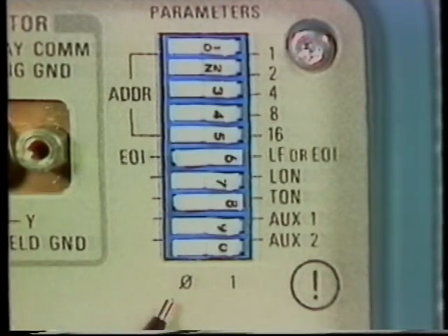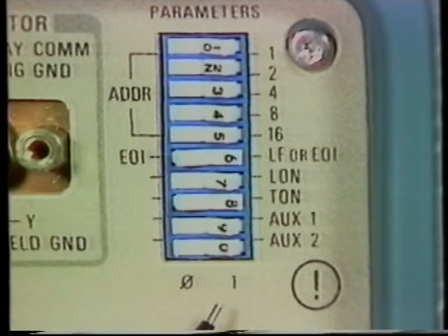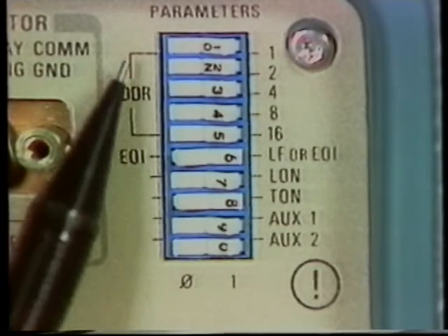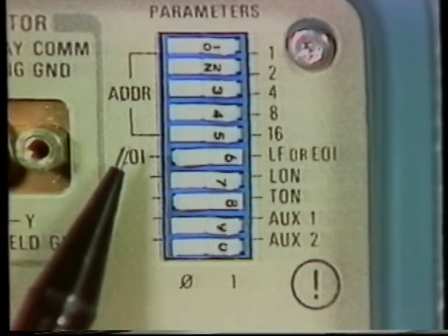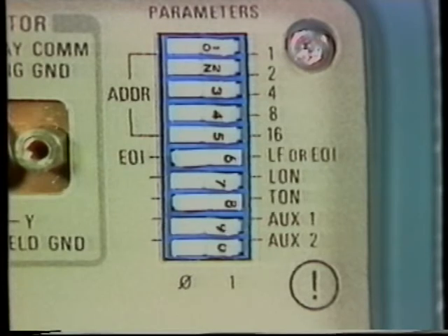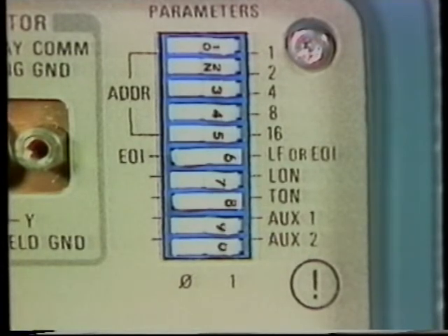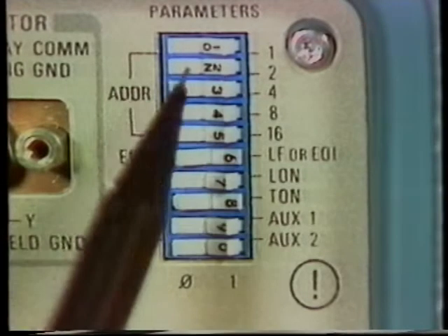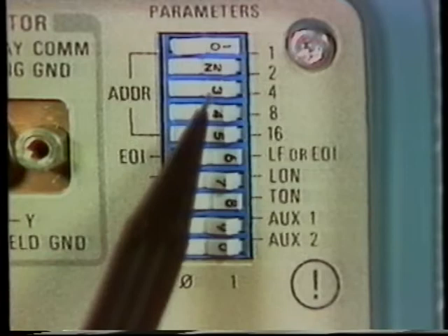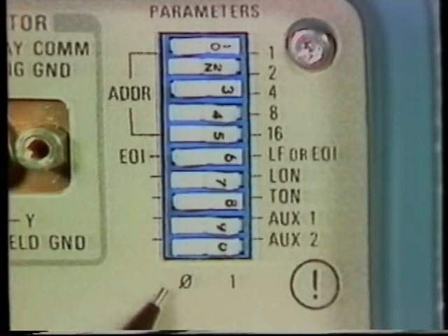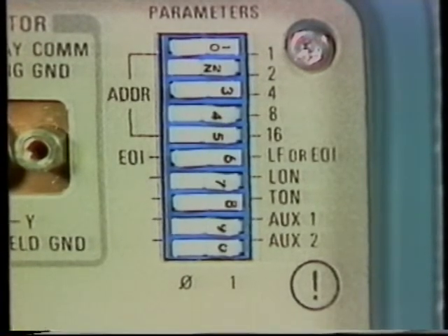The legend on the bottom of the switch shows the open, 0, and closed, 1, positions of the individual switches. The top 5 switches are weighted to set addresses in the range of 0 to 31. The GPIB address of 5 will be set by selecting the 1 side of switch numbers 1 and 3. Switches 2, 4, and 5 will all be at 0, making the total value of all switch closures 5. By taking the sum of the first switch with a weight of 2 to the 0 power, which equals 1, and the third switch having a weight of 2 to the second power, which equals 4, we have a total of 5 set into the address switches.